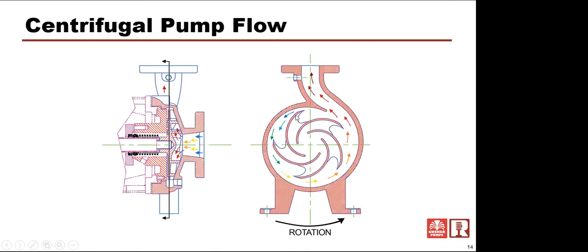Now, when we design one of these centrifugal pumps, this pump may have, if this is a 3x4/8, for instance, which means it has a 3-inch discharge, 4-inch inlet with an 8-inch maximum impeller, we may trim this impeller for proper performance to, say, 7 inches, which means there's going to be even more space between this cut water and the impeller than normal. What happens in that case is that the cut water becomes less efficient, and there's more water that recirculates back inside this pump around this volute. So we lose some efficiency, and unfortunately it's a loss that's pretty normal in pumping systems.